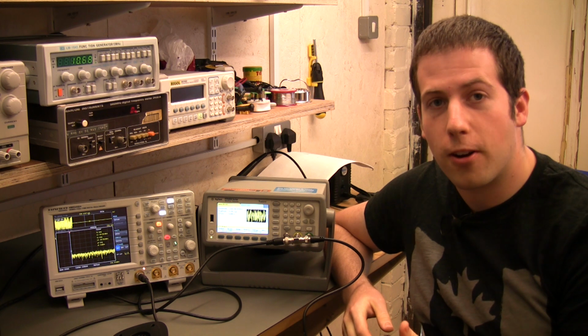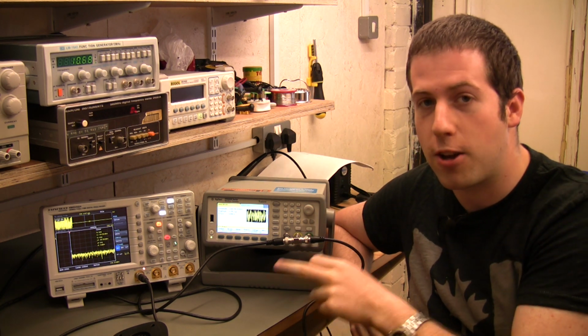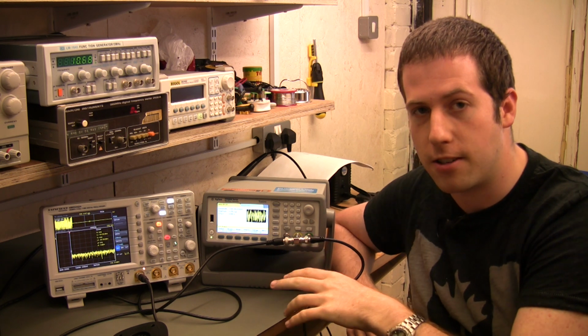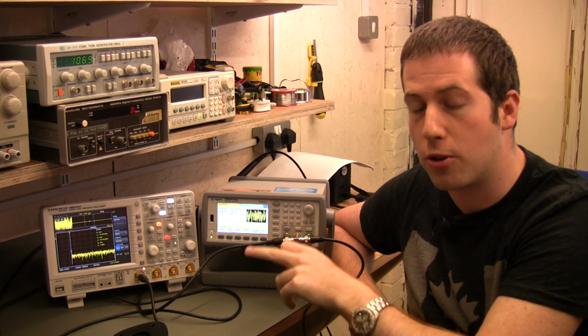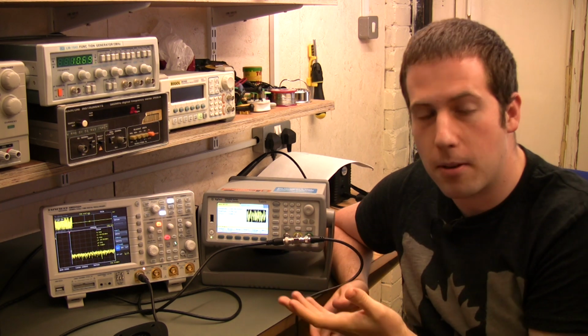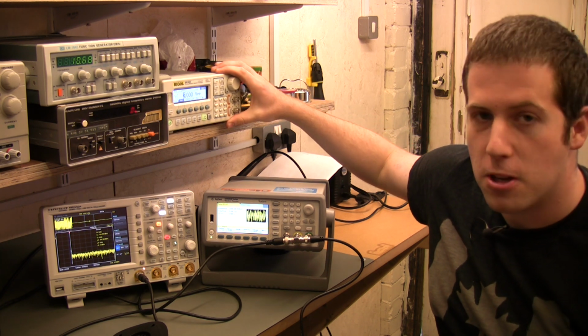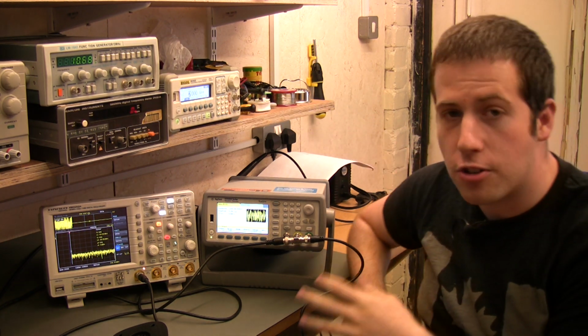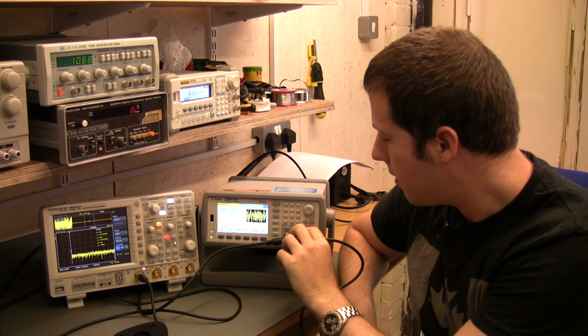One of the features I find quite useful in here is the noise generation capability. I find this is pretty common amongst most of the arbitrary waveform generators, but unlike some of the other ones, you've got a bit more flexibility, a bit more control with this one. Compared to something like the Rigol DG1022, which is the generator we used before now, you can actually control the bandwidth of the noise, that sort of thing. So let's just give you a rough demonstration here.